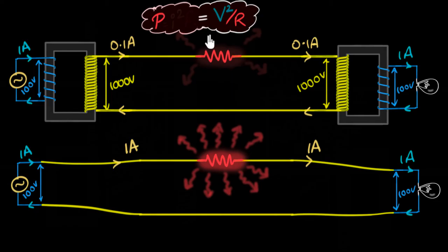All right. Remember where this comes from. This comes from Ohm's law by substituting V is equal to IR. And Ohm's law is always applied across a resistor. So this voltage is not this voltage or this voltage. This is the voltage that would come across the resistor. And that voltage is basically I times R, which means over here, since the current is 10 times smaller, even that voltage across this resistor has also reduced by 10 compared to the voltage over here.